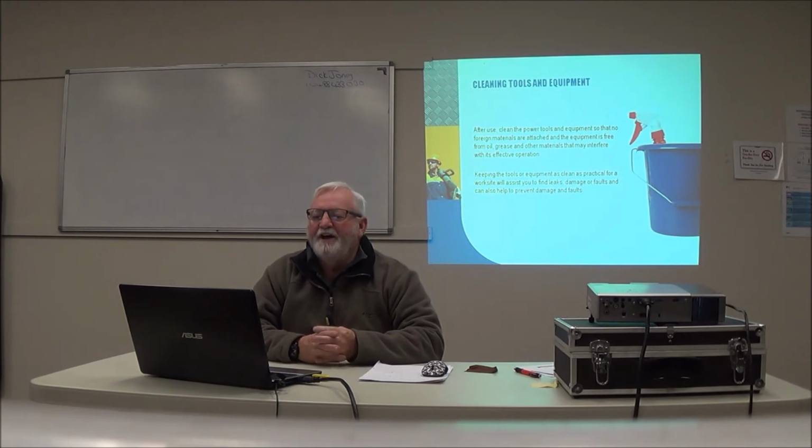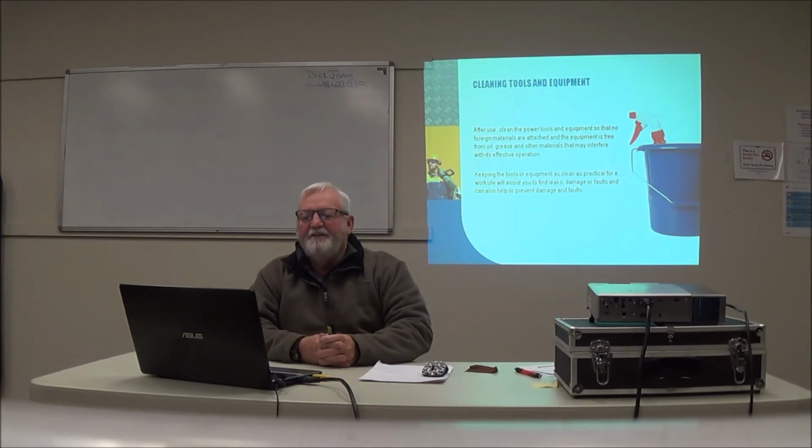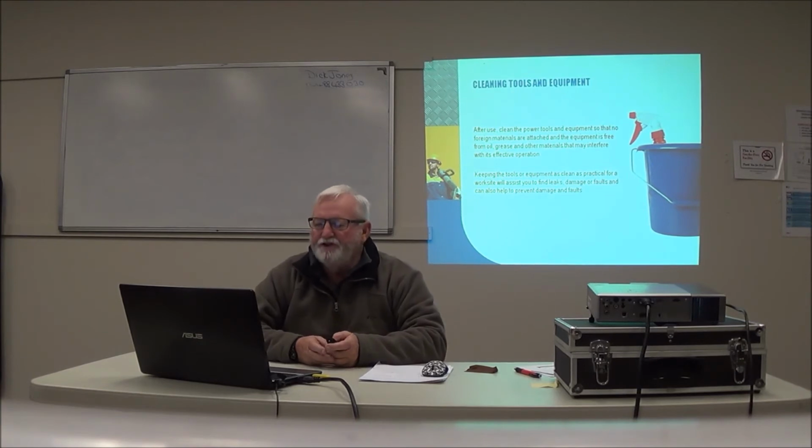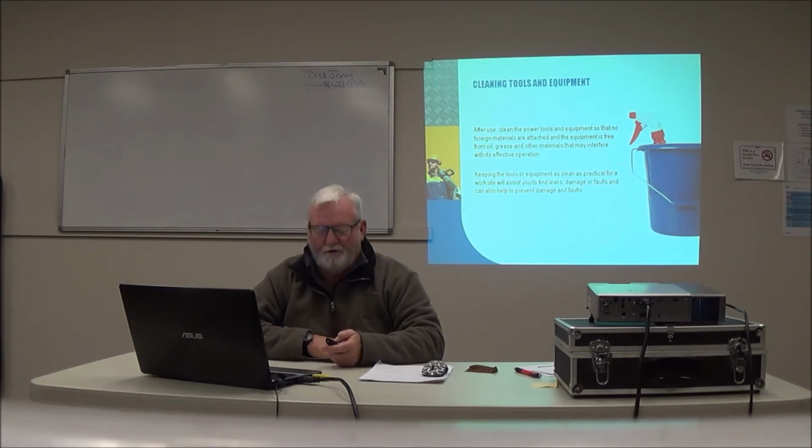Cleaning tools and equipment. After use, you clean the power tool and equipment so that no foreign materials are attached and the equipment is free from oil, grease and other materials that may interfere with its effective operation. Keeping the tools and equipment as clean as practical for a work site will assist you to find leaks, damage or faults, and can also help prevent damage or faults.